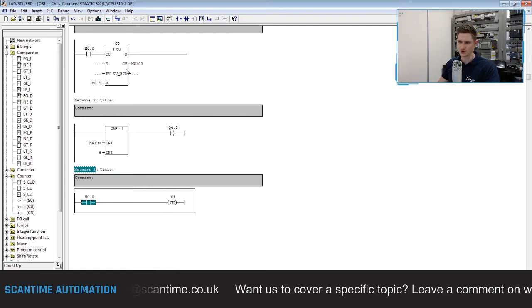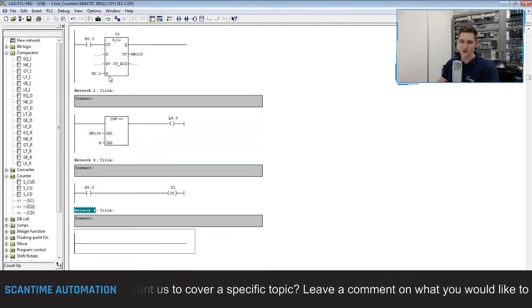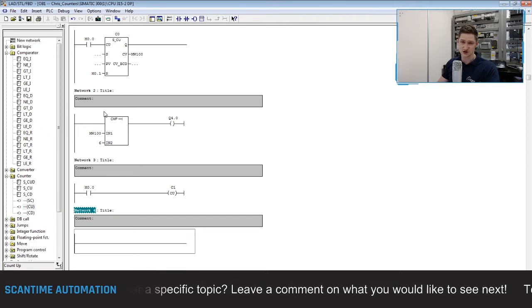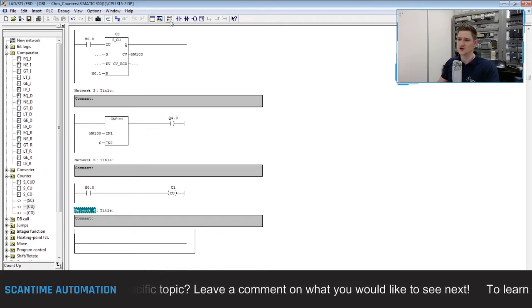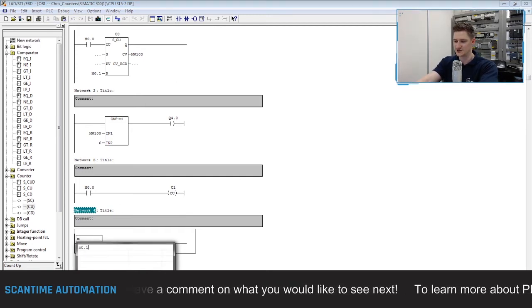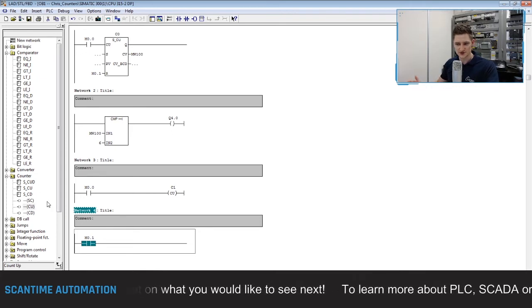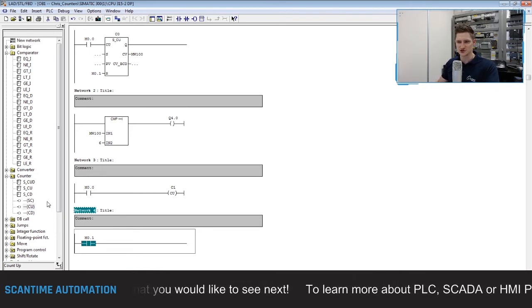Right, okay. So next we want to create a new network, and we need to create the reset portion of this counter, because again, this counter needs a reset just like every other counter. So again, I'm going to add a normally open contact. I'm then going to tie this to M0.1, and inside of this counter folder, you'll notice there's no reset instruction.